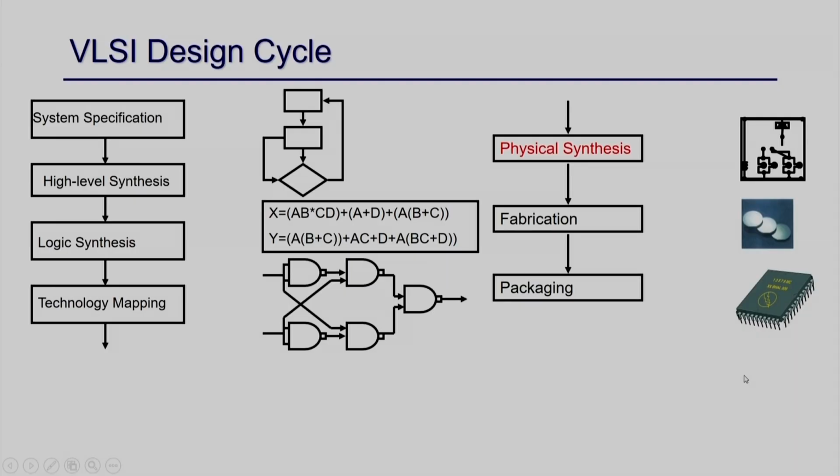Let's start. If you look into the VLSI design cycle, we have already discussed that it starts from some specification, then goes through high level synthesis, logic synthesis, technology mapping, and then physical synthesis, fabrication and packaging, right? We already have discussed high level synthesis, logic synthesis and technology mapping, and we are going to talk about physical synthesis today.